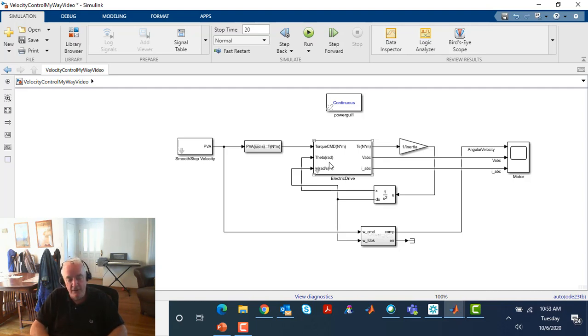The real constraint is how fast can that algorithm run, and actually I have a processor right here, this is an Arduino, might not be the one I'd use for an AC motor, but how fast can a calculation take place on that processor. If you can get this whole field-oriented control algorithm as compact and efficient as possible, it means you can run it at higher rates.